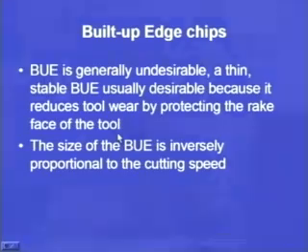So, if the formation is taking place in such a manner that the exact geometry of the tool that we have designed is not getting affected. First point, the built up edge is not very thick. Second point, the built up edge is a stable built up edge. Then if these three conditions are satisfied, then sometimes the built up edge is desirable. Why is it desirable? Because it protects the rake face of the tool against wear. So, the excessive wear of the tool point geometry will not take place. This built up edge will cut the workpiece, and the surface finish that we will get under these limiting conditions will also be comparable, or will also be good.